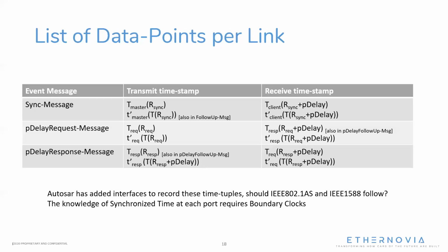And then we receive this pDelay request message on the other side. We record the local timestamp because we need that for the follow-up message and for the whole pDelay process. But we also associate this with the synchronized time at exactly that point in time when the pDelay request message was received.